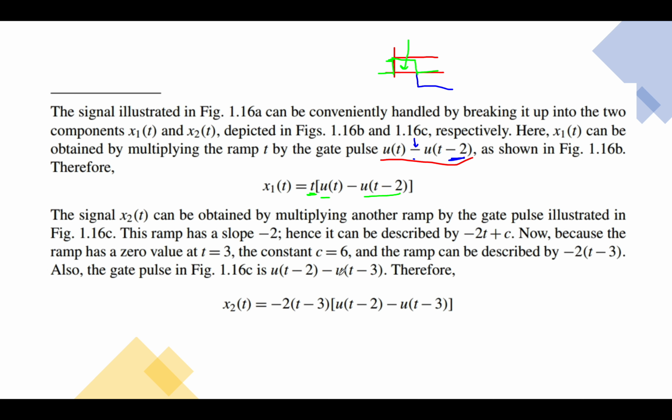And finally, and this describes a little bit how to get the equation for that second line, I then take the second line, whose equation we determined was given here. It begins at 2, so I use a time-shifted step function at t equals 2, and then it turns off, quote-unquote, at 3, so I subtract a step function at 3. That then windows this function between 2 and 3.